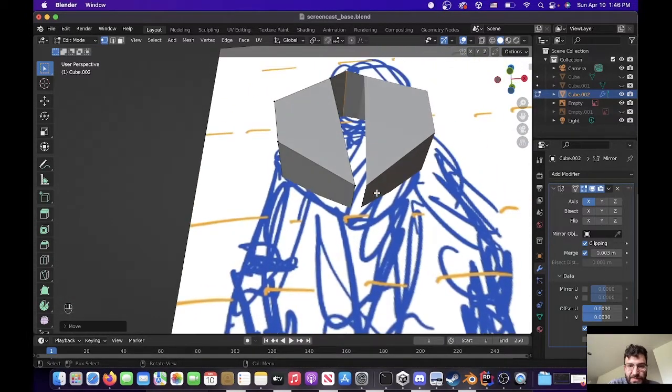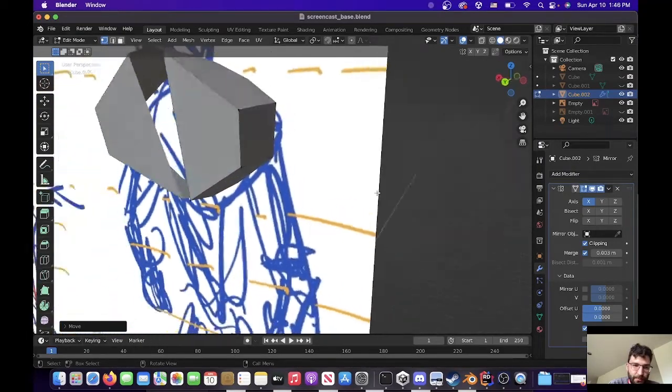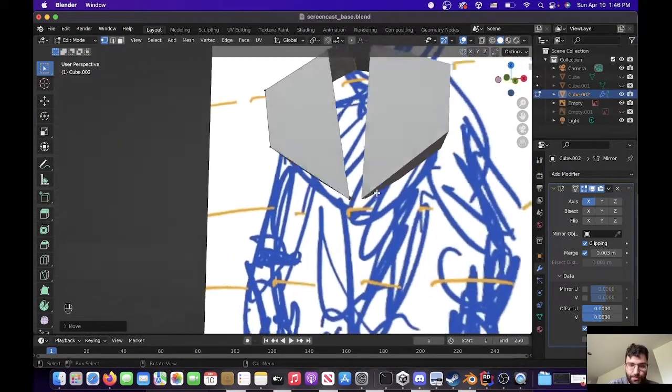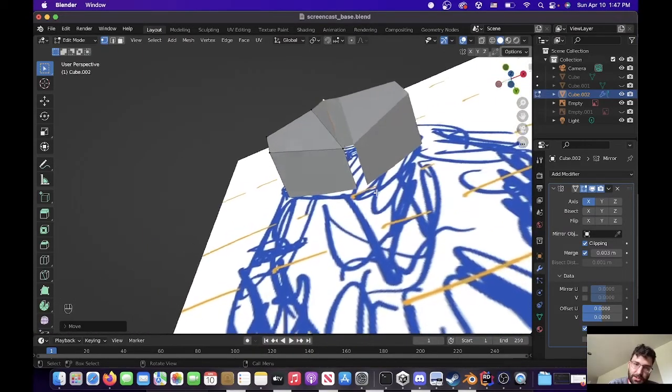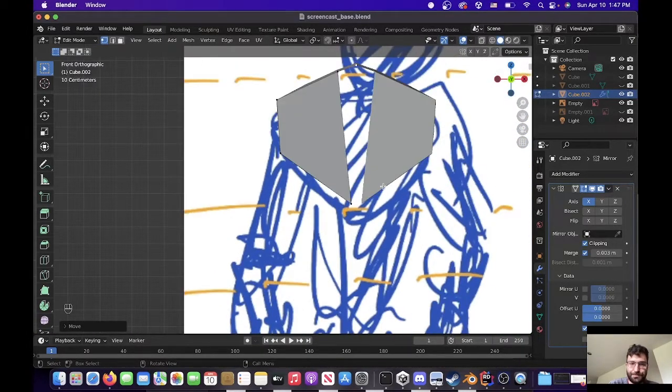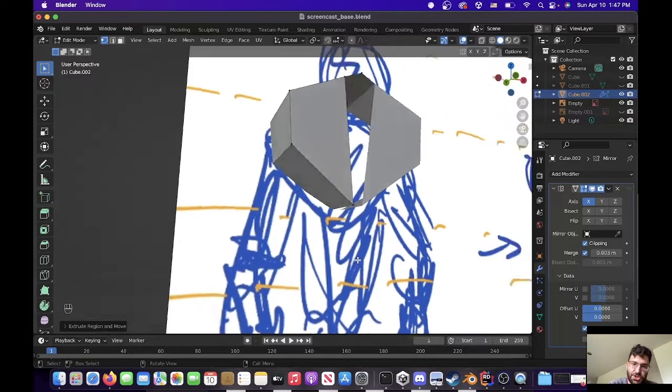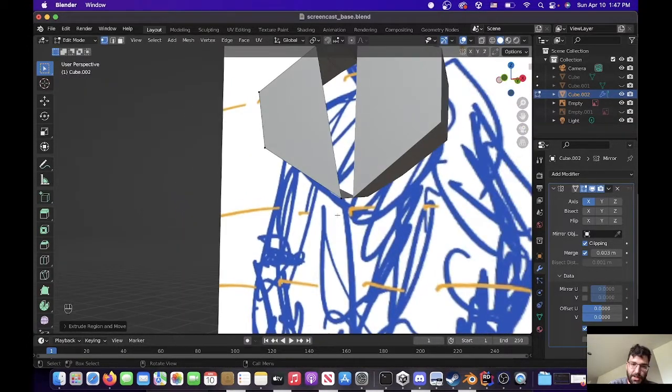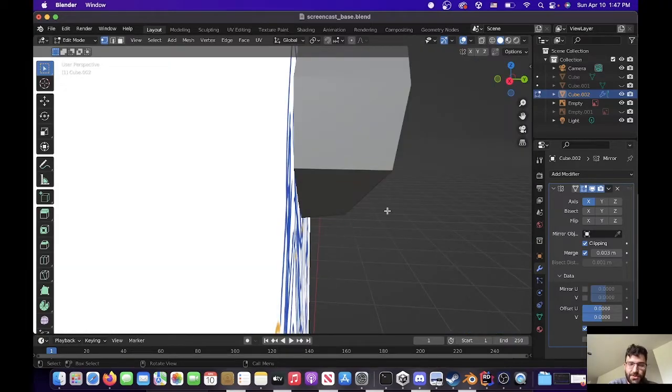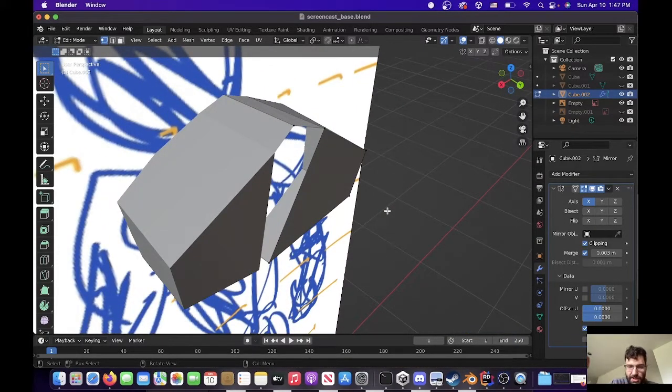Now we're almost ready to close this up. So we've got this open box now and we need to make it a closed box. So if I go back to the front view, we're going to learn a new command, which is extrude. If you hit E, you can see that? I took my edge. Where is it? Come on, edge. So I have 2 points. Extrusion just means you take one thing and you duplicate it and you translate it. I can extrude a point like this, a single point. I can extrude an edge like this,